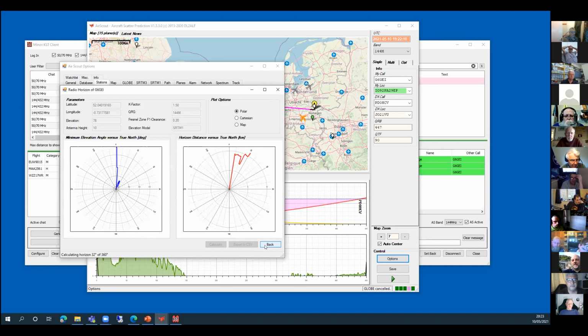Now, obviously, for north, it's absolutely terrible, and then to the east, I'm actually not so bad, which is roughly right, because my house is looking southeast, and everything to the southeast and to the east is lower than me, and everything else is higher than me. So as it works its way around, you're going to see that I need to elevate the antenna more. Oh, so the closer it is to the middle, the better. Yeah. In terms of takeoff, the left graph suggests that the takeoff to the north is terrible because you'd have to basically have it vertical. Basically, yeah, which is why I can't work anyone to the north from home except by some amazing conditions or an aeroplane. Normally anything that's between west and north is non-workable for me, and you guys will be spotting stations I can't even hear.